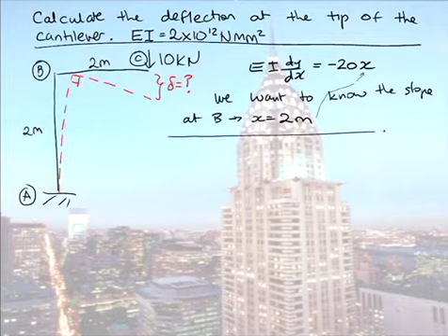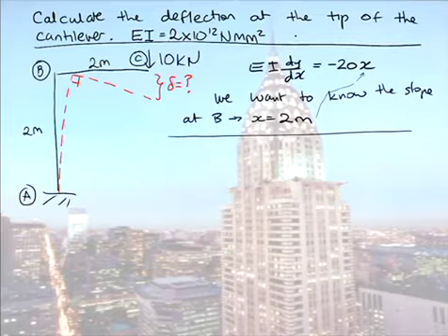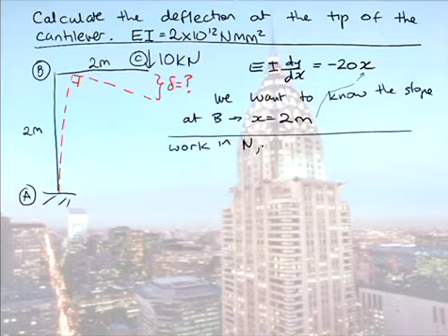Now, as yet, I haven't dealt with units, but we need to start looking at units here. Back in the original question, we were given EI in units of Newton millimetre squared. So we could either continue to work in kilonewton metres or decide to work in Newton millimetres. Normally, I would work in kilonewton metres and convert this to kilonewton metre squared. However, today, because the solution I have in front of me does that, I'm going to work in units of newtons and millimetres.